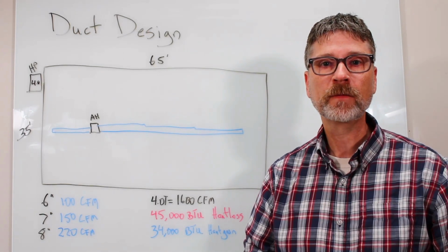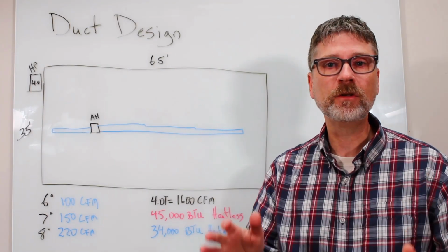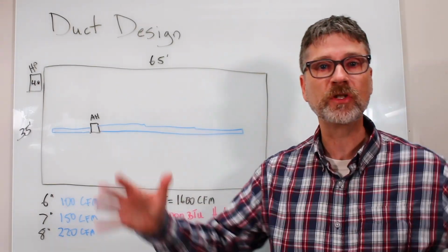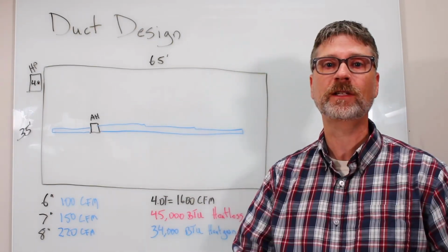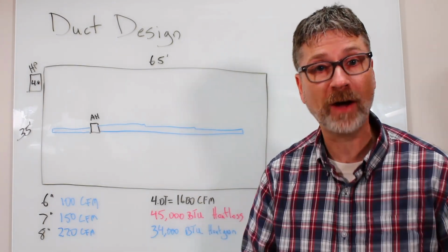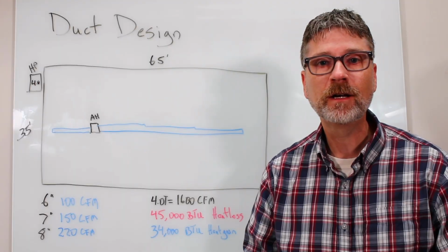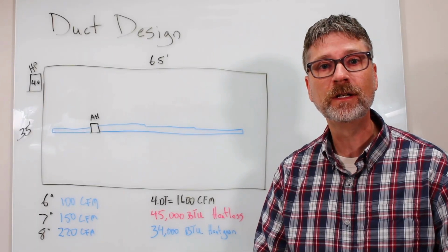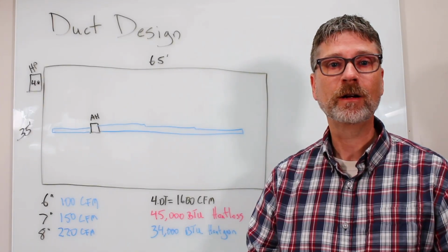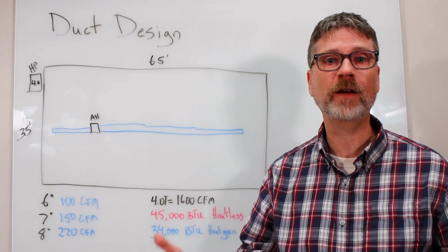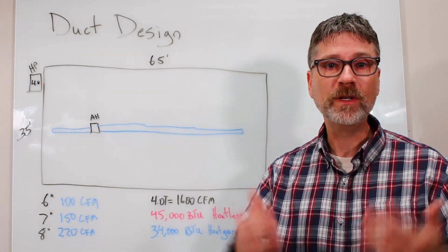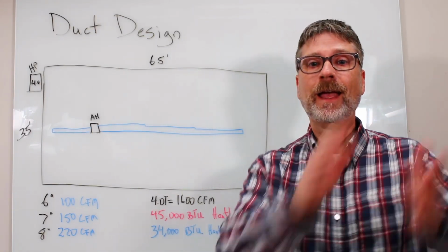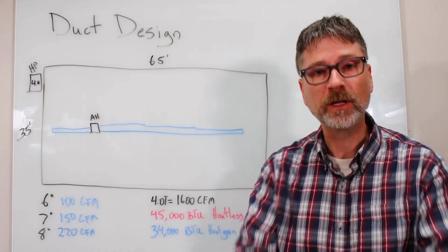In heating systems, different units heat the air to different temperatures, thus you get very different amounts of heat energy in the same volume or velocity of air. A heat pump may only heat the air to 95 degrees or about a 30-degree delta T, while a gas furnace gets to maybe 110 degrees, that's maybe 45 degrees for a delta T. An oil furnace, though, well, that really cooks the air up to about 140 degrees, 75 degree delta T. Very, very warm. When designing a system, it's important to know both the requirements of the AC system and the heating system, preferably in CFM.